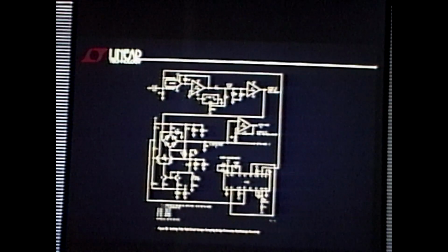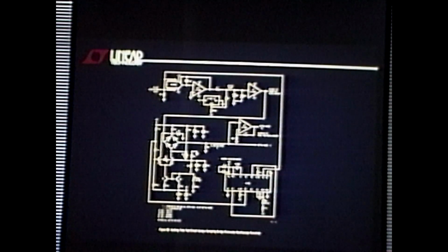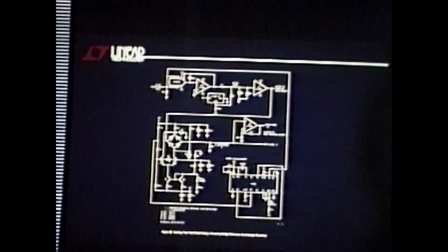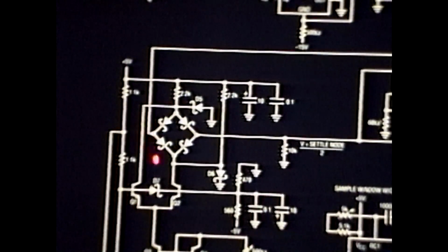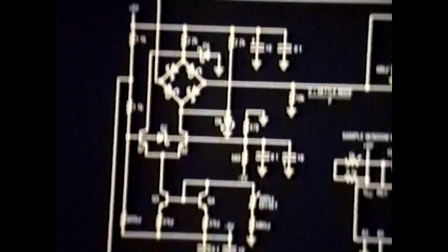And the way this scheme works is, here's the basic circuit up there. I've gone to Schottky for a little better clamping. Now I've just got a fast open loop buffer. This comes over to here. Look at this bridge here. That is a sampling bridge. What we've reproduced here is the front end of an old-fashioned 1960s era, what I call true no-fooling sampling scope.